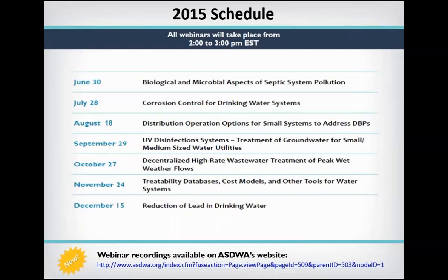So the way I hear this question is, well, there could be other sources of fecal pollution that enter into the waterway during storm events, and undoubtedly there is. And we saw that with our general fecal indicator data as well. But when you use a source tracking method that will only identify the human portion of that contamination, then you can zero in on what's happening just with the human pollution source and not the other one. So if we had tried to do this analysis with a general fecal indicator, we did not see a pattern between dry and wet weather events, because there's chronic fecal pollution there, but it's from different pollution sources.